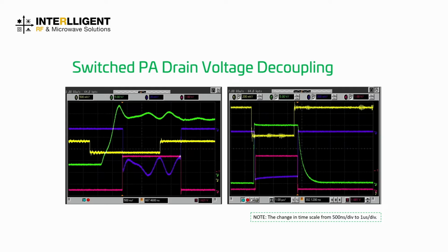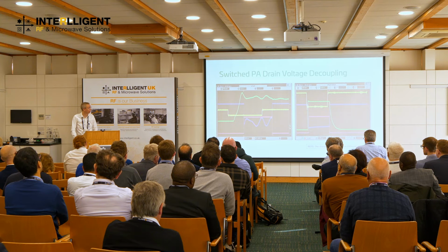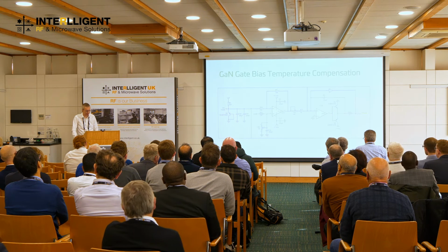Unsurprisingly, this was the low frequency decoupling on the PA. We actually found we had enough local decoupling on the regulator that provided it, and so we could pull out, I think it was a microfarad capacitor. And then we got the green trace on the right there, which is lovely. Great pulse fidelity, lovely decay down to 0 volts, and fast as well.